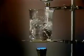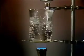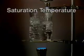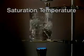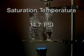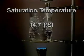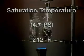At any given pressure, there is a corresponding temperature at which water will boil. This temperature is called the saturation temperature. For example, at standard atmospheric pressure, which is 14.7 psi, the saturation temperature of water is 212 degrees Fahrenheit. When pressure increases, as it does in this boiler, the saturation temperature also increases. At 1000 psi, the saturation temperature of water is 545 degrees Fahrenheit.